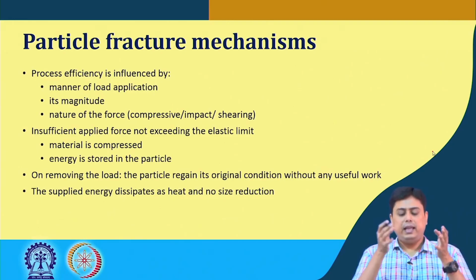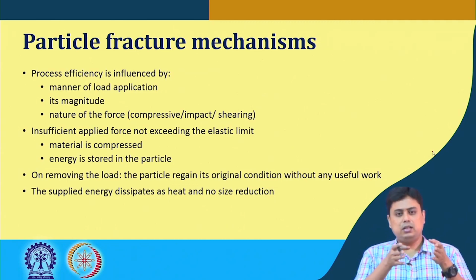So, the energy that we have supplied has basically gone to waste in terms of size reduction, because it did not affect that; the supplied energy dissipates as heat and is stored in the particle. So, we have to cross this elastic limit to make size reduction happen.